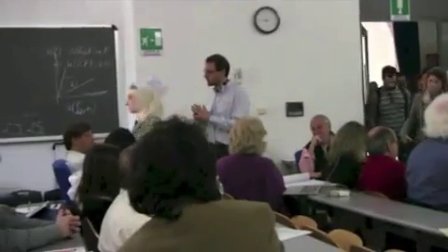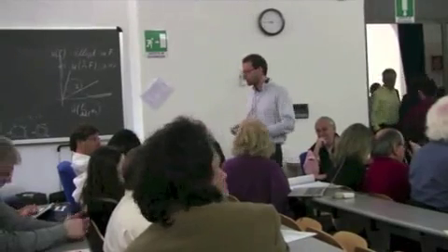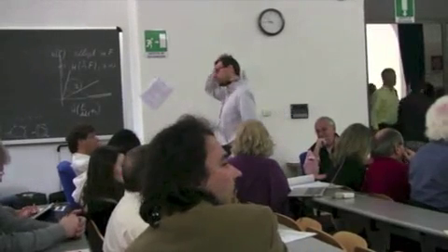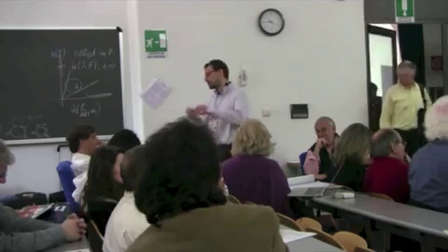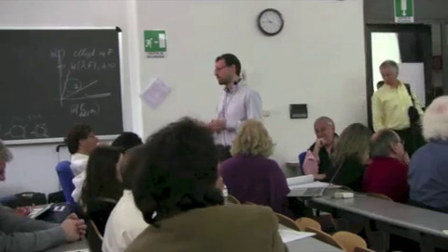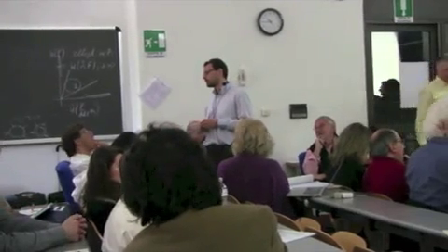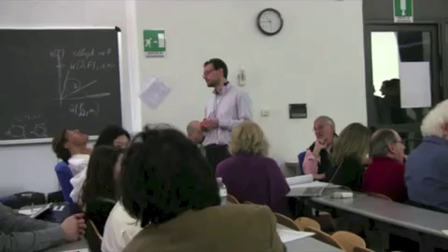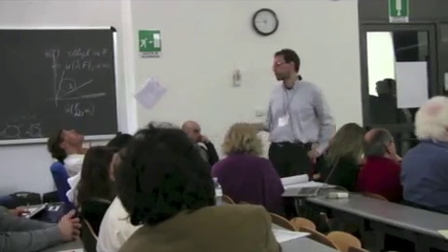Are you talking about the crystal plasticity model? Crystal plasticity model, yes. So I think the first one who obtained this equation was Gurtin in 2002, and it's just an extension of the Schmid law. No, okay. This is something much earlier that was done by Eshelby from a material science perspective, but he actually included screw dislocation, so it's fine.